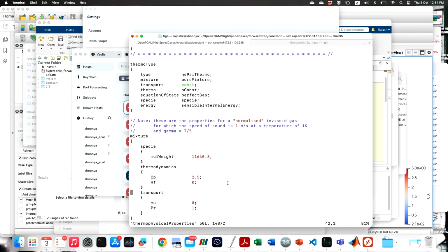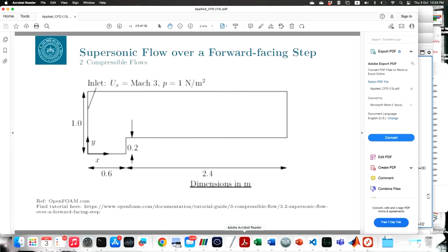Anyway, the mu value is 0. So, the Reynolds number does not matter, but we just use the Mach number information of 3 and we got other values, right. So, you can play around with all the quantities that you have in your hand, but you have to ensure the dynamical parameters do not change, right. So, if you have Mach number here, Mach number should not change. If you have Reynolds number, then Reynolds number should not change. If you have both of them, then both of them should not change, right. So, this is one example I wanted to show you, so that you can understand this.